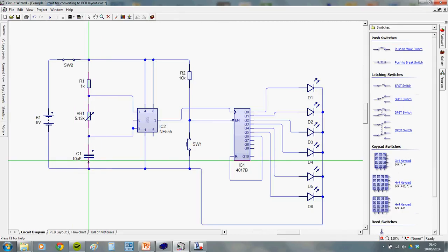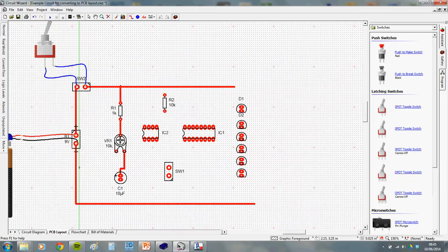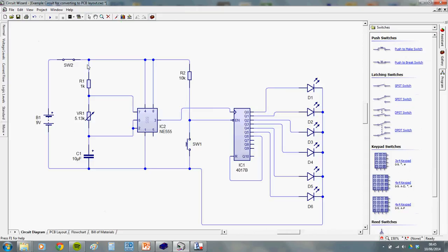Right, other end of the capacitor went to 0 volts, and because we put the rail in there, we can just go straight down to it, like that. Okay, so I've done this kind of pathway there, which is this whole bit there. Now obviously there's a bit more missing. I've pretty much done all of that bit so far, but I have got between pin 7 of the 555 timer and between the resistor and a variable resistor I've got a connection.